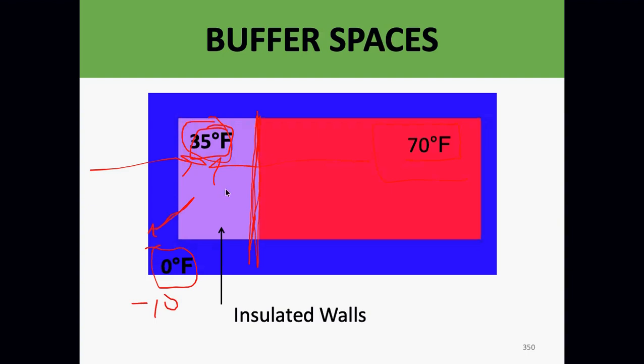The reason I keep asking about installing things that are going to freeze, and you're going to hear me say this over and over and over, is because when we install furnaces, if you install a high-efficiency gas furnace or a high-efficiency oil furnace, where we're talking about a condensing furnace, it puts off water as it burns, these furnaces will freeze in areas like this, and all of a sudden you get a no heat call on the coldest day of the year. Okay, it's a pretty bad situation.